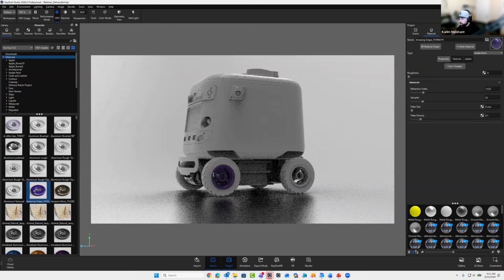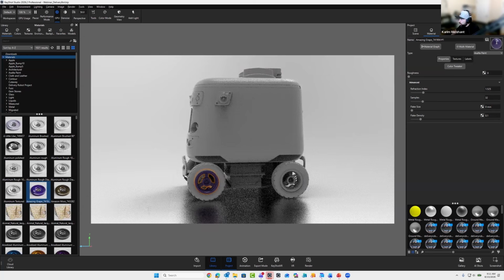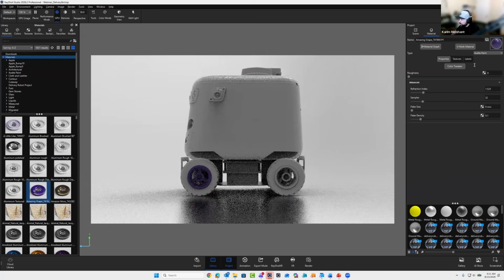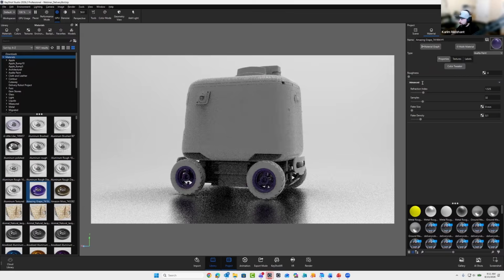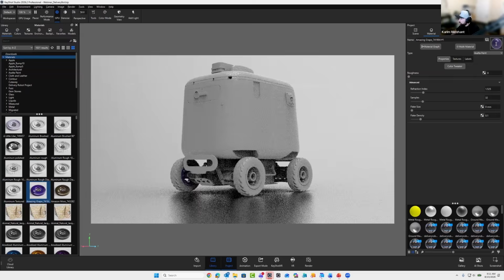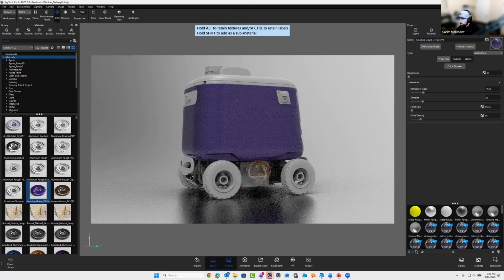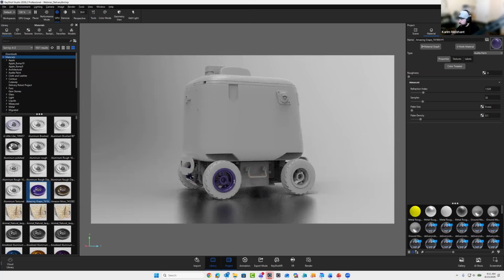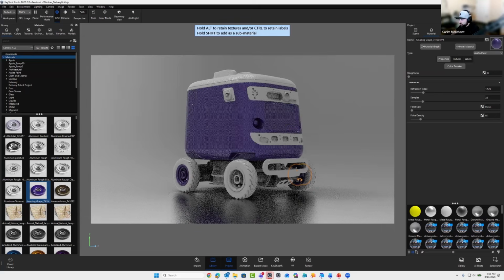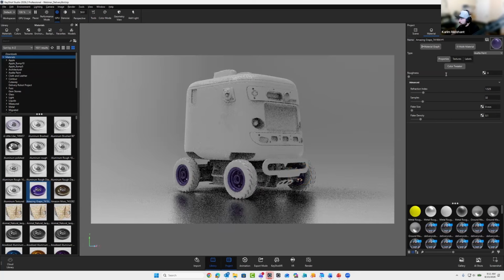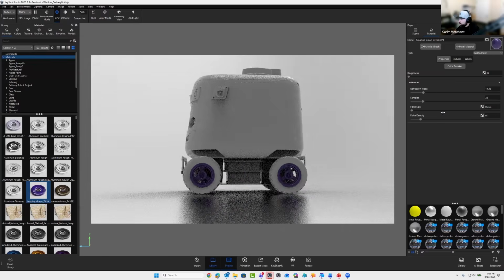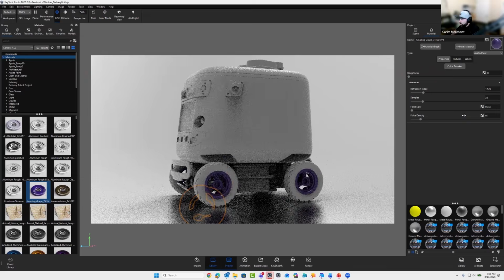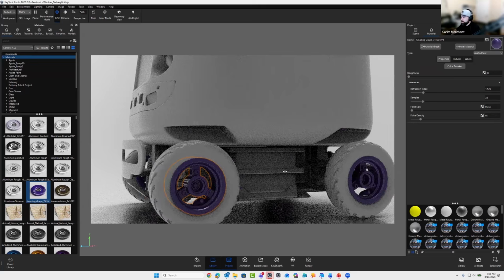So the way I would link with the material open, you can see here in the top right corner, there is a little thumbnail showing a preview of that material. If I actually grab that thumbnail, I can apply materials directly from the thumbnail, and you'll notice no window pops up. KeyShot automatically knows that if I'm using that material to apply it to different places, it's going to link those materials together. And then when I go in to make an adjustment to the materials, which I'll zoom in here real quick, you'll notice that those materials all update together, and we can see that happening on both of the wheel hubs right now when I add flakes and I add roughness. So it's a really useful way of working to make sure all your materials are linked from the start, but you can do it in KeyShot.